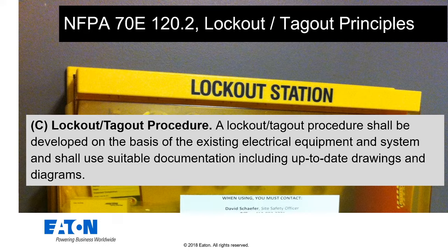Now, I'm going to use that phrase. It doesn't say that you have to have it, because I'm hoping that somebody out there decides that this probably deserves a public input. In my opinion, it does. The more people that tell the 70E panel that they really need a requirement that you have an up-to-date one-line diagram or single-line diagram, I think it's critical. But in this case here, it just says it shall include. It doesn't say it must include. And shall use suitable documentation, including up-to-date drawings.